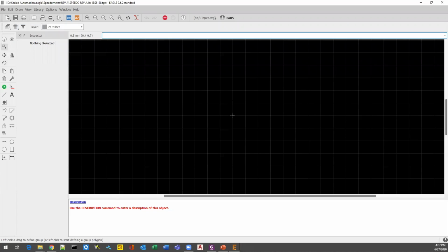With this grid in place, let's put in the first pad. And those pads happen to be 0.8 millimeter wide and 0.9 tall. So over here on the pad, come in, I'll click that. Ooh, and I got the wrong kind of pad. So we're going to have to edit it. Oh, sorry, that's the problem. I hit a hole instead of SMD. It's right next to it.